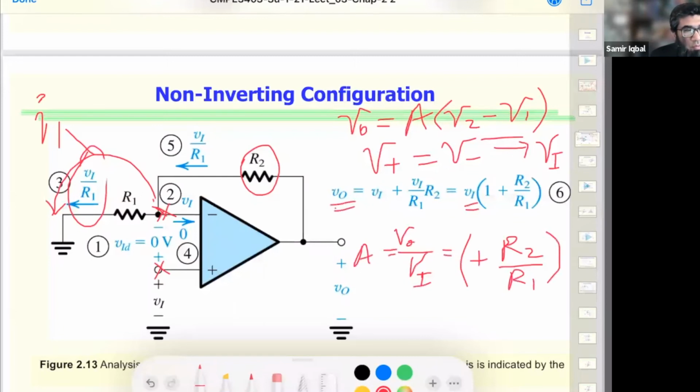Again, the most important thing that has happened is I've taken the infinite gain from the op-amp, and now we are controlling the gain by adjusting the resistances that we use, right? So R1 and R2 are acting as a voltage divider to feed the output voltage back to the inverting input terminal, and it is giving us control over the gain of the circuit.